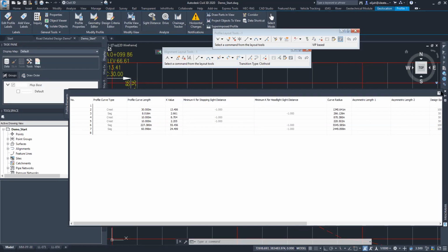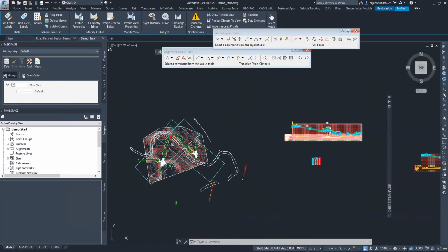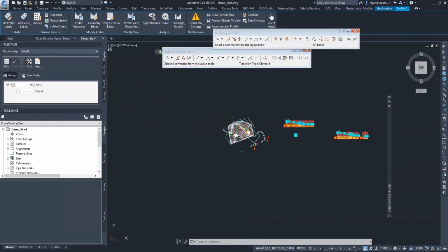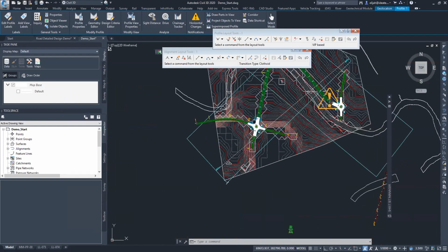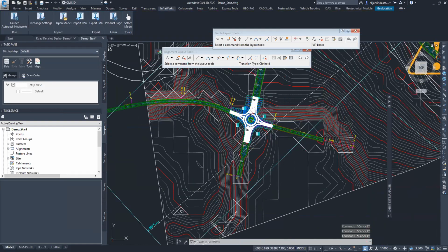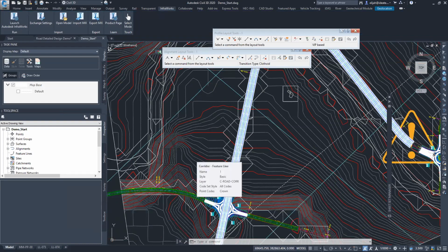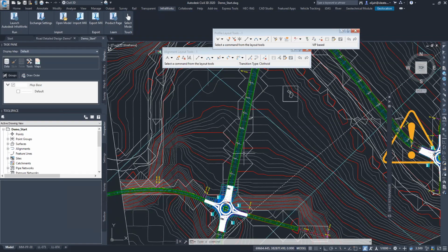So that basically means I've verified and I've checked that all the design requirements as per the required code of practice, they meet the minimum values that are specified. So the next thing before I go further is to now generate the center line points that the surveyor can now put into their total station, or I can push it to them through Magnet Enterprise or Magnet Field, and therefore they should be able to receive that information in their field controller and start staking it out, as you have seen in Moad's presentation, basically showing the process of staking it out.